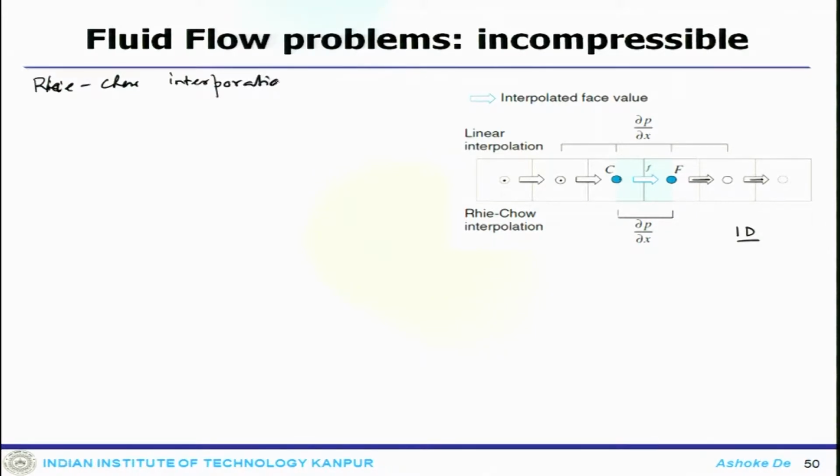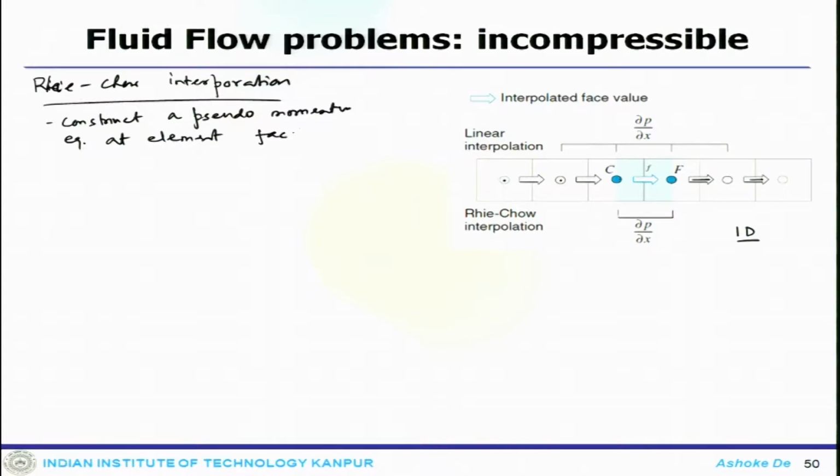What it does in this particular method is that it constructs a pseudo momentum equation at the element face, with its coefficients linearly interpolated from the coefficients of the momentum equation, which are based on the cell center.